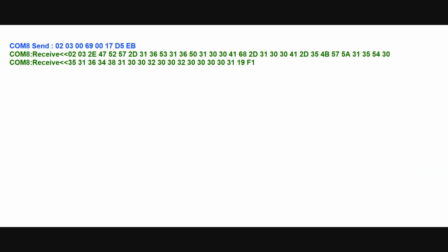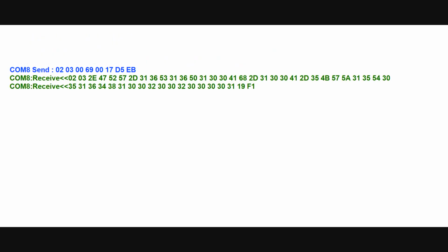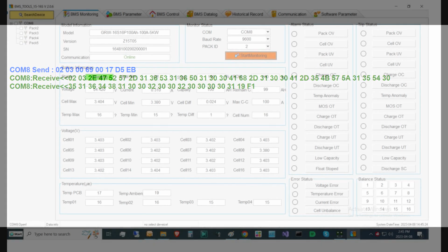On occasion, the BMS software will send out a different 16 bytes to the batteries that look like this. When compared to the request for the battery data, the difference can be seen in the makeup of the 2 strings. Where the battery data request string looks like this, the new string looks like this. The first 2 bytes in the new string are the address for the battery. The difference in these strings, as I have been able to determine, is that the new strings are a request for a serial number for each of the batteries.